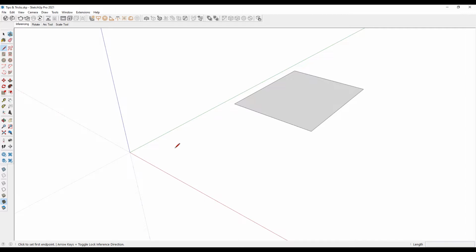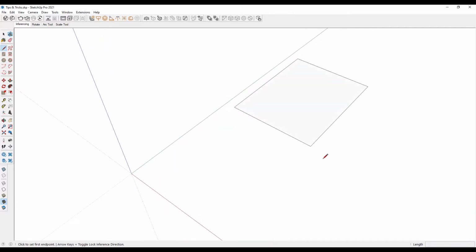If I'm about to draw something, let's say we've already drawn a rectangle here. As I hover over the corner of that rectangle, you see an endpoint show up. As I move along this line, it says that it's on edge of the surface. As I move further along, it's also going to inference and let me know where that midpoint is. And the same thing over here. But if I start going over onto that face over there, it's also going to tell me that I'm drawing on this face, and it's letting me know where I'm about to start my drawing from.